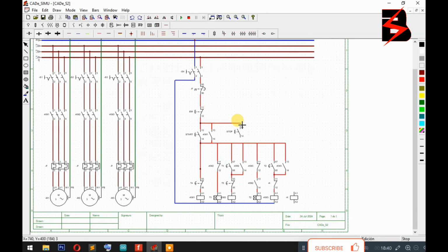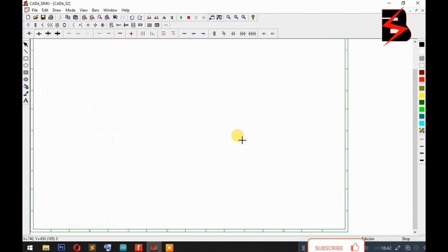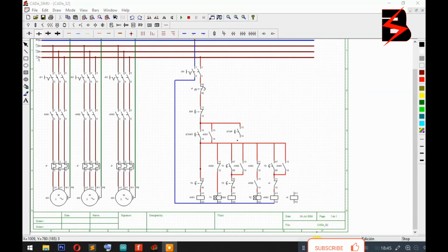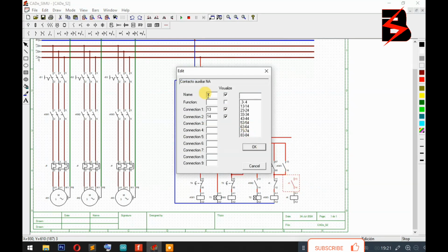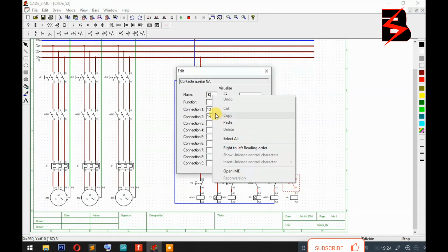Then I'm going to have my cable from here. I power this normally open. Then from this normally open, I'm going to come and power my relay. But I'm going to power my relay through the normally open of contactor 1. That means contactor 1 must first start before this relay operates. So I'm going to have here normally open of contactor 1. This is contactor 1, KM1. Don't forget.